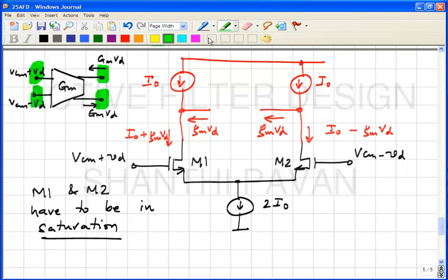And what do we need to know to figure out if the transistors are in triode or saturation? All that we need to know is the drain potential at M1 or M2, correct? Basically M1 and M2. And one way of figuring this out is to apply some VD. Choose some arbitrary VD, apply it, and you look at the drain potentials of M1 and M2, and we figure out if that is high enough. And what is the meaning of high enough, Avinash?